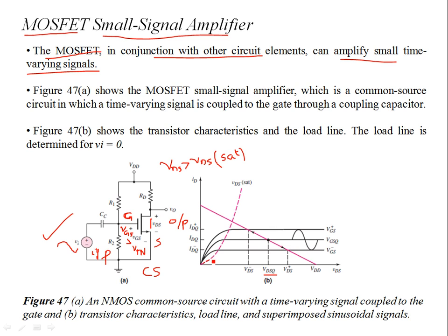This dotted curve shows you the points, for the given VGS, where the transition occurs from non-sat to sat regions. So for this VGSQ, this is the transition point. If the VDS is beyond this point, then you're operating the transistor in the saturation region. In the saturation region, the current is not dependent on VDS. We have talked about this time and again.